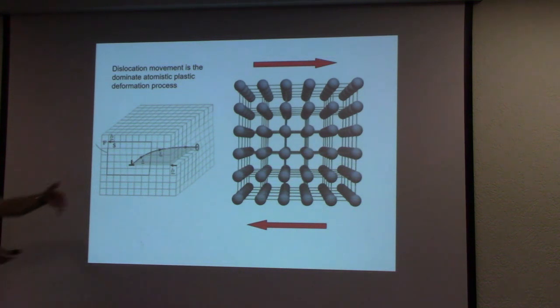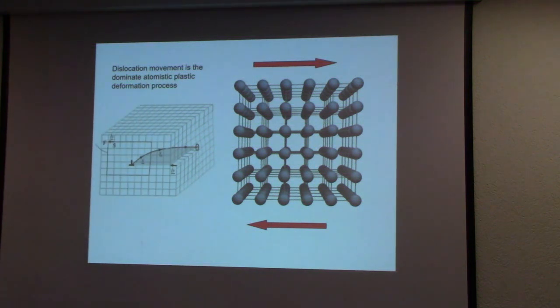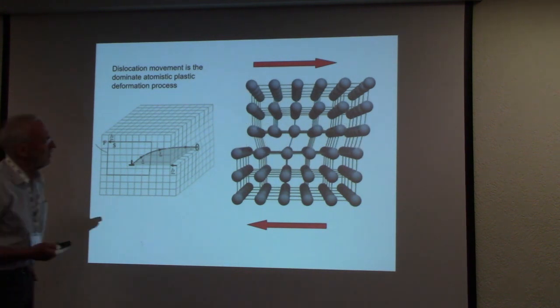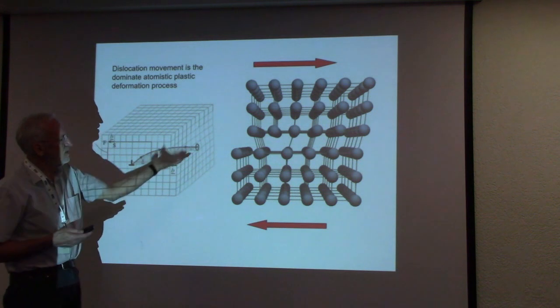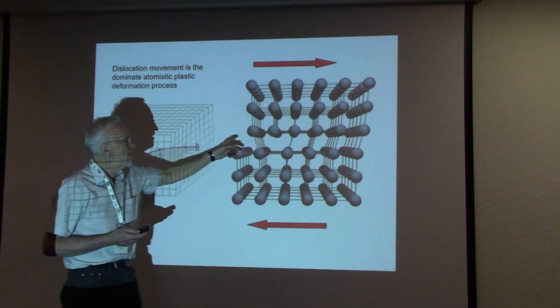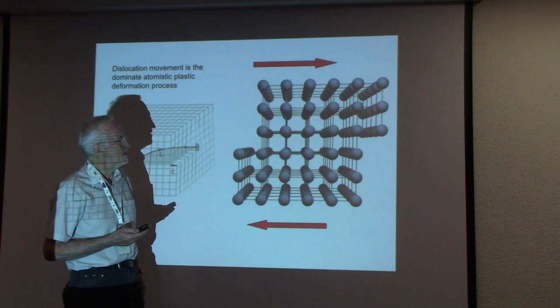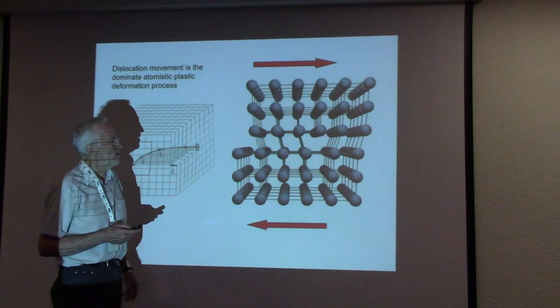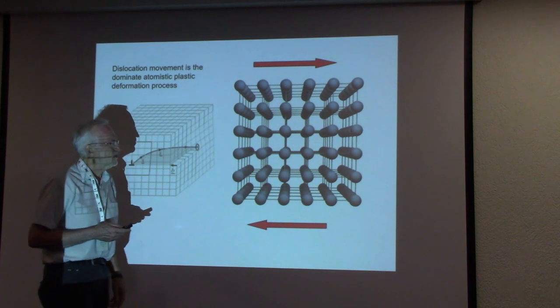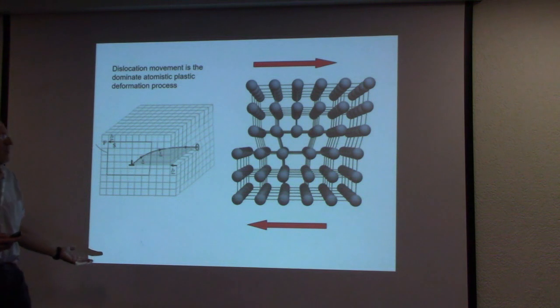If you elastically deform, you simply change the spacing between the atoms. But when you plastically deform, you do not destroy the lattice. The only thing that happens is that such defects move in the crystal. So if you deform it, you simply go from here over this way. This was really 100 years ago a big question: how could we deform a metal and the crystal structure remains?